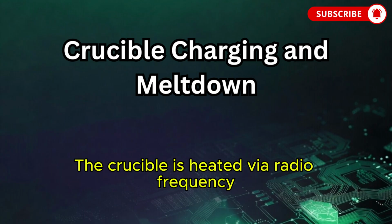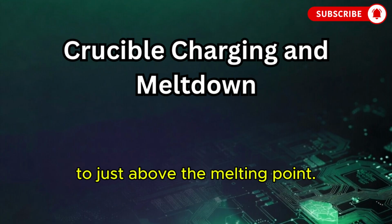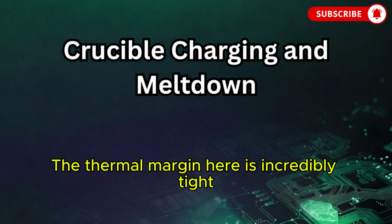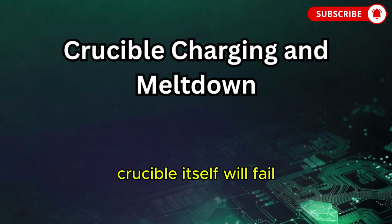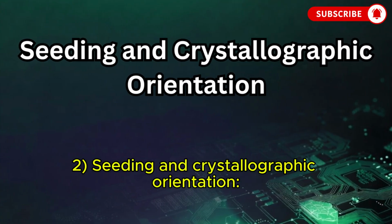The crucible is heated via radiofrequency or resistance heating elements to just above the melting point. This meltdown phase takes anywhere from 2 to 10 hours. The thermal margin here is incredibly tight. Overshoot the temperature by too much, and the structural integrity of the silica crucible itself will fail, causing it to collapse under its own weight. 2. Seeding and crystallographic orientation.